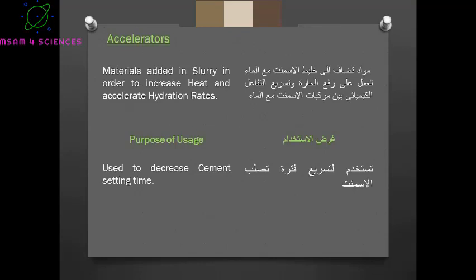Accelerators. Chemical materials added in slurry in order to increase heat and accelerate hydration rate. The application of this product is used to decrease cement setting time. So it will make the process of hydration take place rapidly.